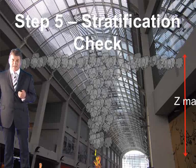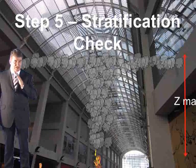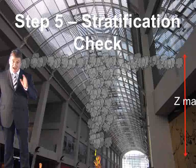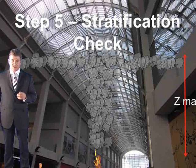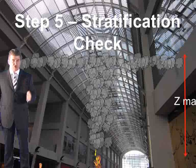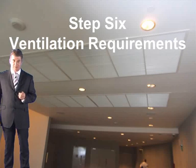Step 5 is the stratification check. Now, in this case, because the clear layer height is so low, in other words, only 3.9 metres, then stratification can be ignored as it's not a problem with such low heights. You don't have to carry it out at those heights, 3.9 metres. We can move straight on to step 6, which is determining the ventilation requirements.